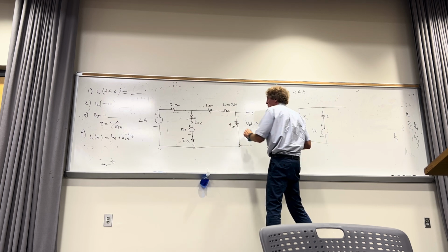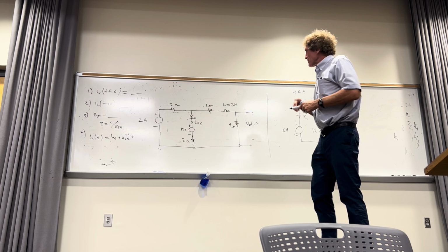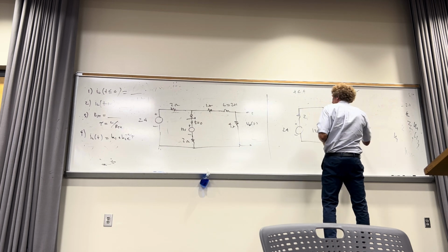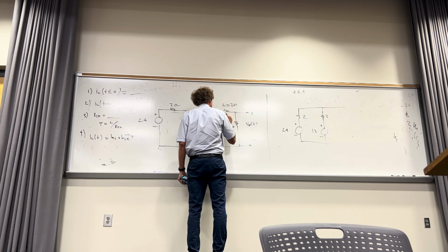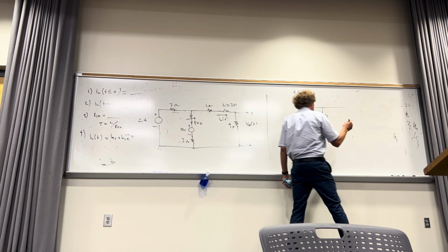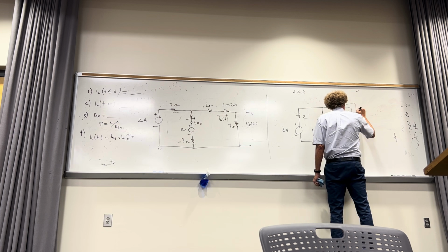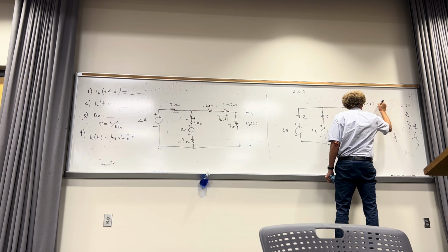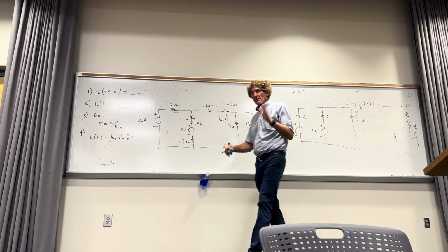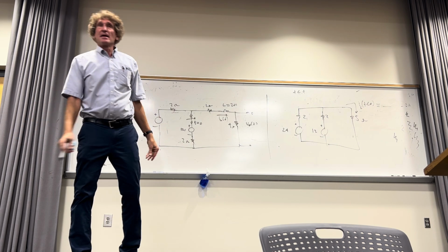But I have 1 ohm and 4 ohm. Can you all see that's 5 ohms? How many see that? Just represent it as 5 ohms. And I didn't put this, but I'm going to assume this is the direction of current IL of t that I'm after. So really, what I have here is 5 ohms, and I'm after this current. This would be IL for t less than 0. I have to make sure everybody sees that. Do y'all see what I've done here? Now, how are you going to solve that?